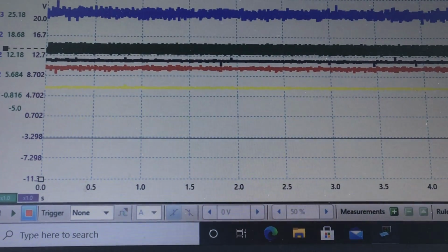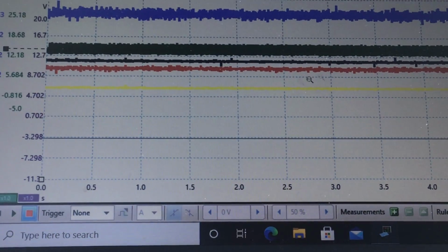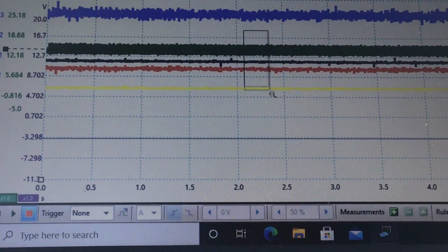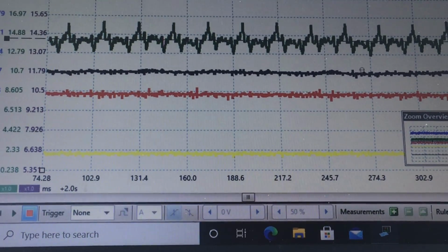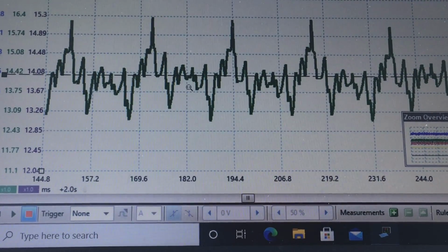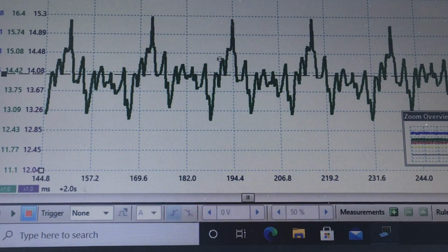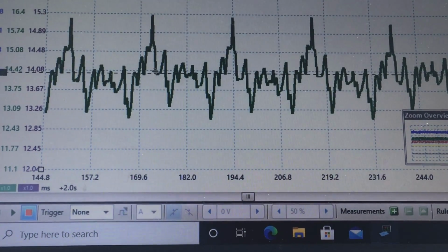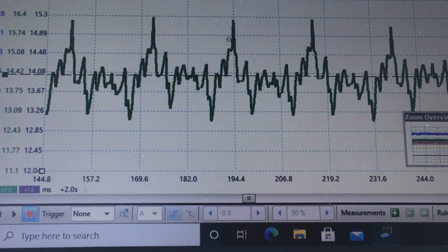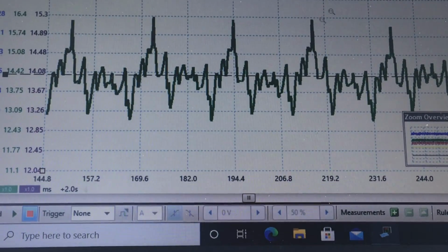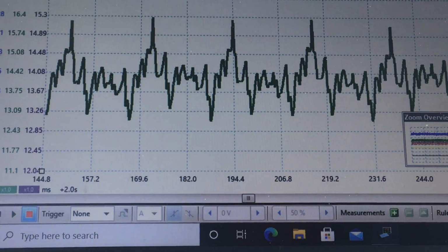One thing I want to say, let's take a look at the commutator bars. This thing has got 250,000 miles on it, and they're kind of nasty. I've seen better Hondas. That's a worn motor, it's probably seen better days. Right here there could be a little dead spot, but the inertia will pull it through. Nonetheless, it's something to keep an eye on when you're testing the condition